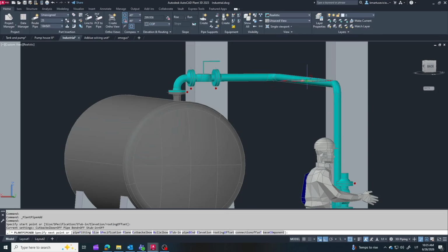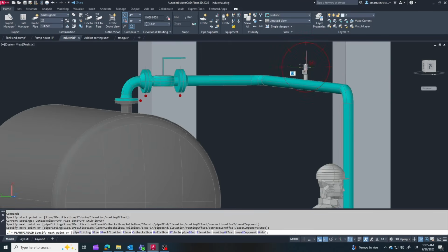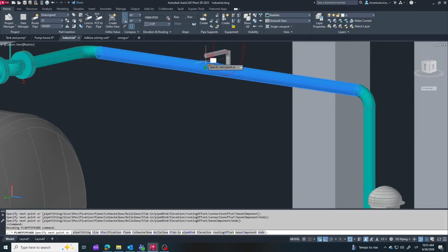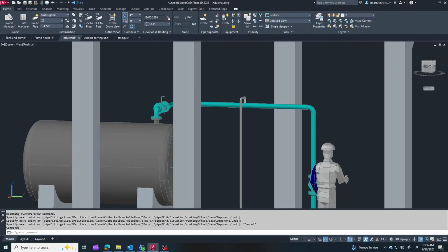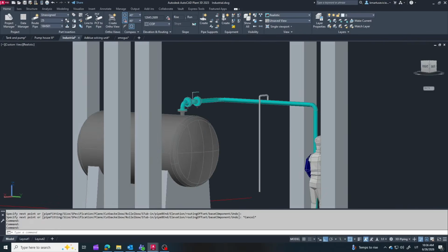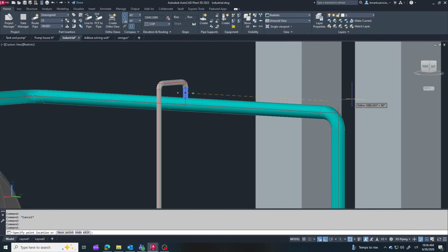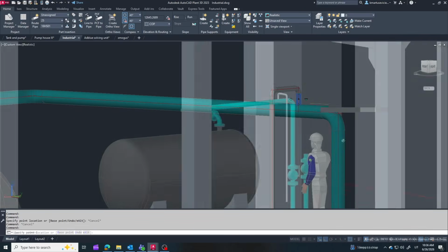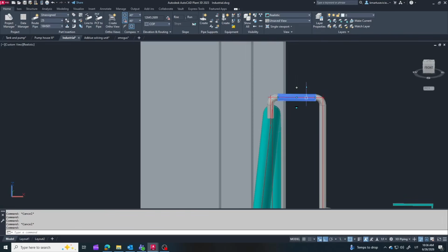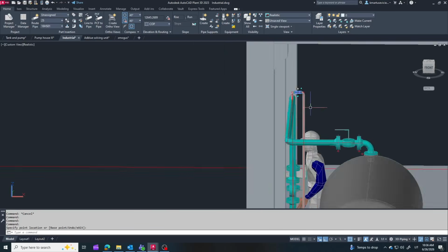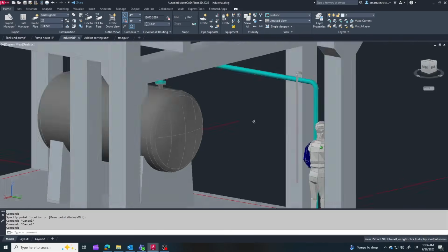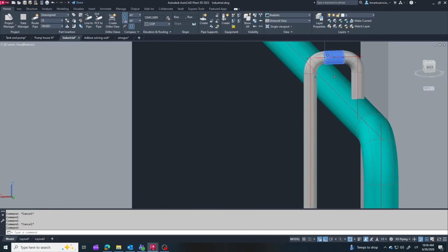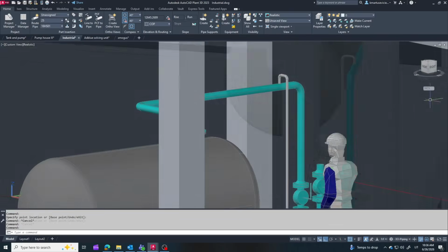We've already talked about drains at the low points. Now let's look at the opposite situation. High points. Whenever the piping creates a high point, air can become trapped there. That's why vent connections are often installed at the highest points of the system. They allow air to be released during filling and operation, helping the system fill properly and preventing air pockets. A simple rule to remember is, low points need drains, high points need vents.